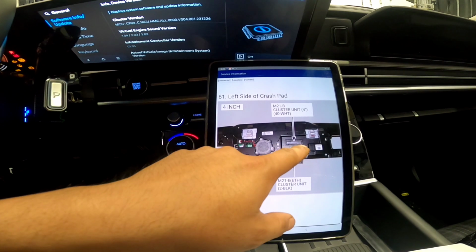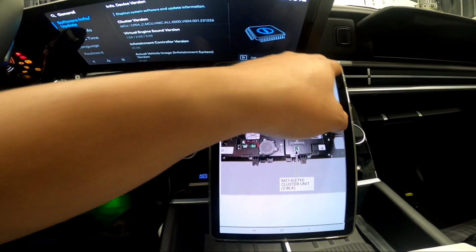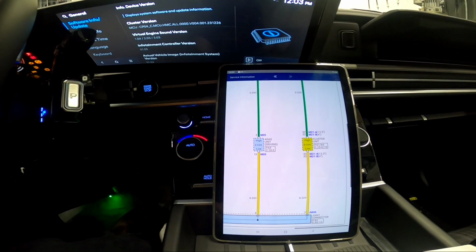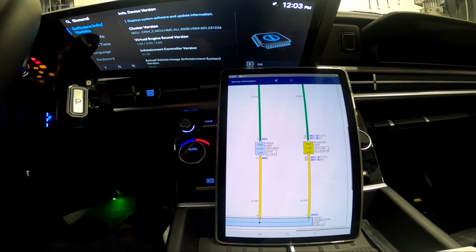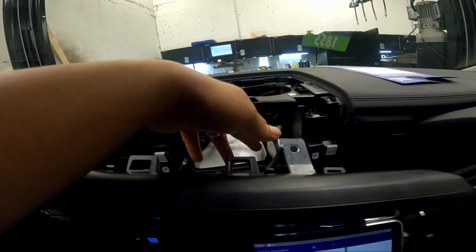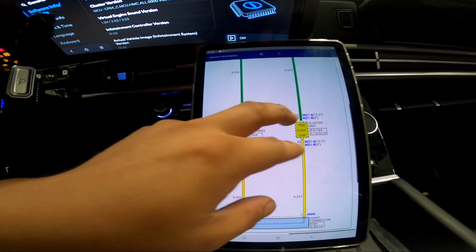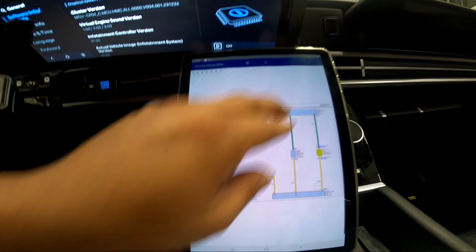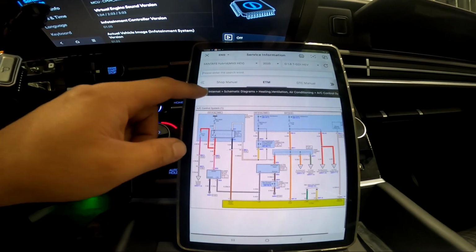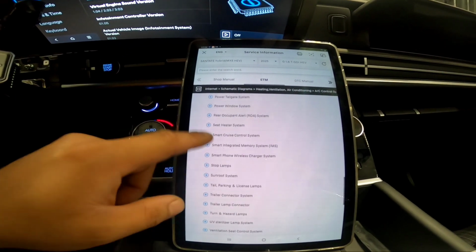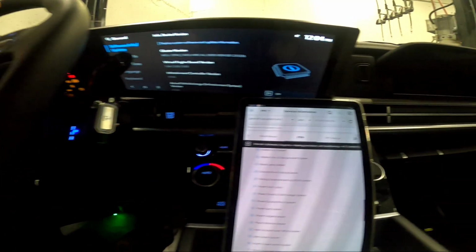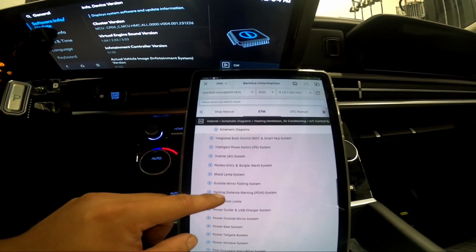Okay, so we're using the 4-inch cluster wiring diagram, because if it's a 12.3 it's a different setup. There's gonna be a unit itself under here, but I cannot see any unit there. So first thing first, let's go to our cluster unit and then check our power and ground there. But we know that our cluster is on. I just want to double check that.